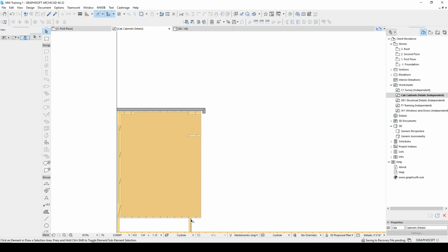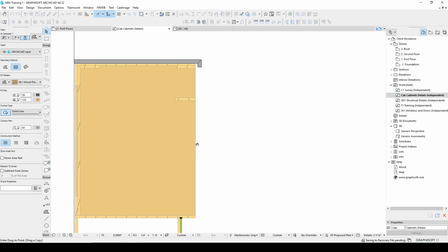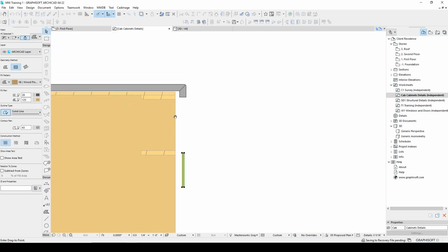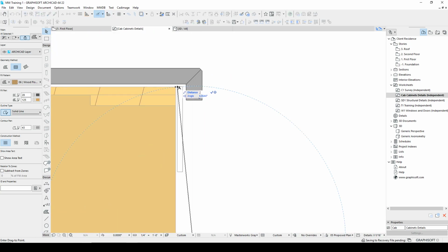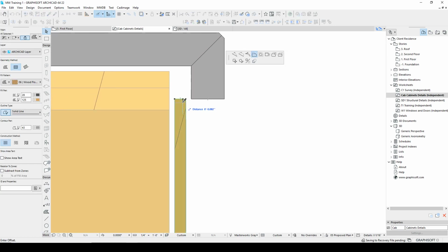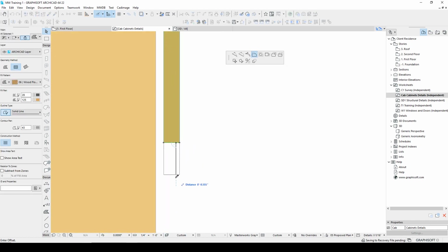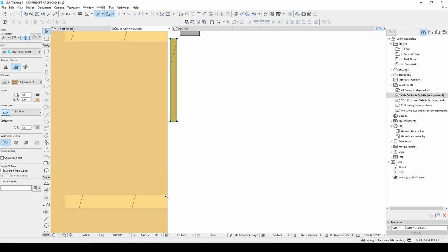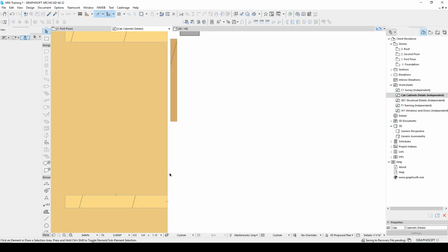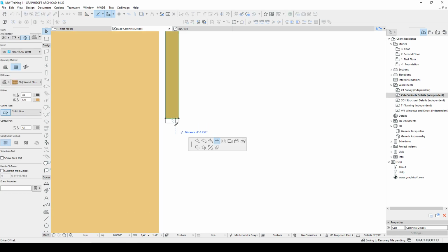And if you want to go ahead and do cross sections of the doors and drawer fronts, we can do that too. And I'll do that. And this has an 1/8 inch space for the hardware. This door needs to come down so that it's only 1/4 of an inch above the bottom of the stretcher. And it looks like we're going to need to bring this down just a little bit more so the door can clear 1/4 inch over. Make this front come to, I highlight this edge and get the tick mark showing.